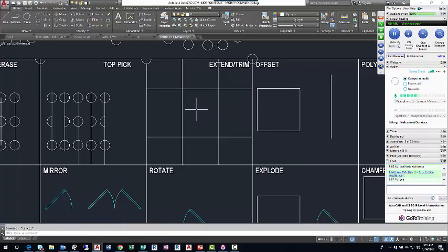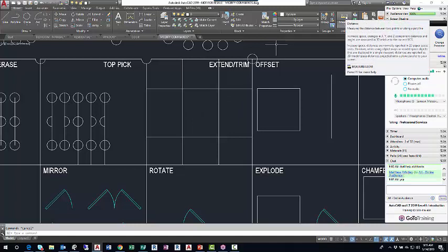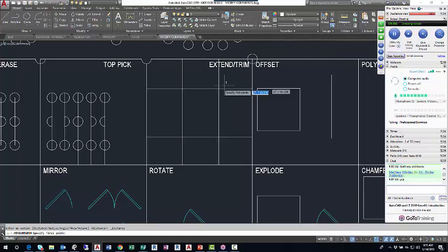However, I should mention some commands you don't have to do that. Some commands you can just start another command. With the, I want to say from memory, the distance command we used yesterday to measure the window drawing, if I click distance, I do one click, two click to measure the distance between these two vertical lines. I'm not really in the command. I'm sort of in the command, but now if I try to start another command, sometimes there it goes. I had to click it twice to get that command to restart. So sometimes, just to make your life easier, hit escape to cancel the command you're in, and you can start the next command with some more relative ease.